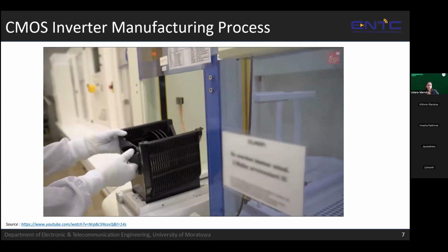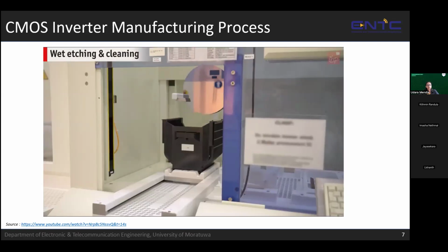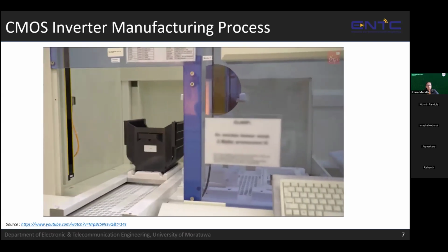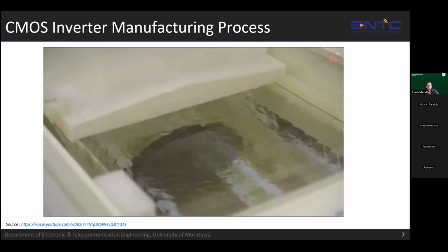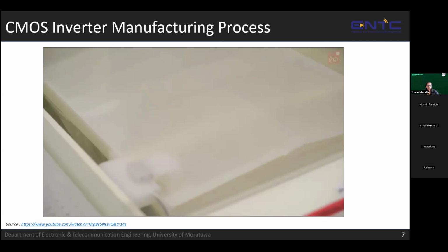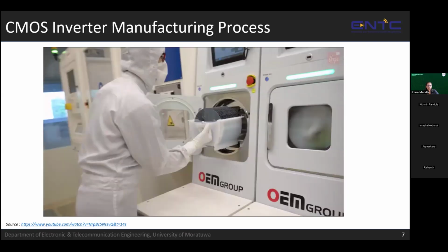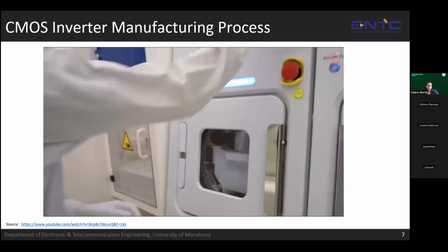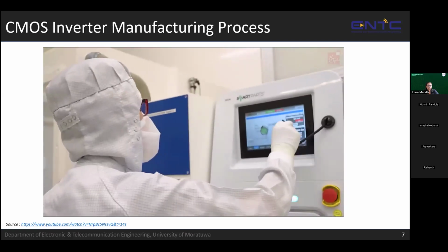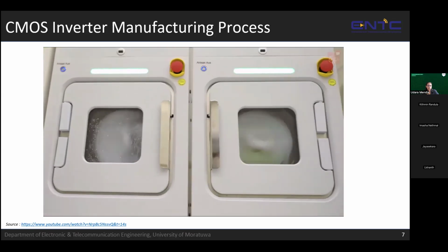To remove surface contaminants such as organics, oxides, particles and metal impurities, we use a combination of chemicals in the initial wafer cleaning process. A batch of wafers is immersed in a special etch bath for a short time and then rinsed with water. In this section, we have a large variety of equipment using different chemicals not only to clean the wafers, but also to etch away entire layers of different material.